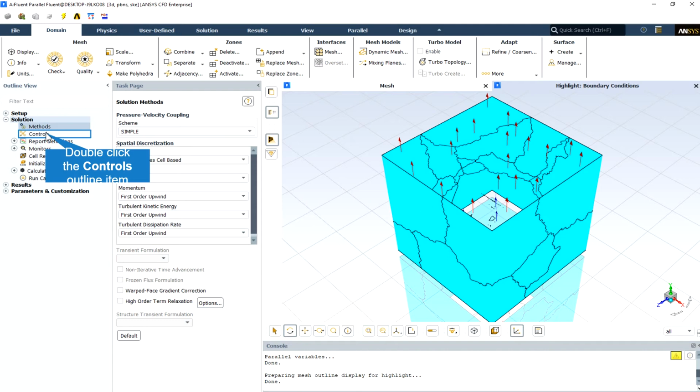For example, if you are running a high Mach number flow calculation that has an initial solution much different than the expected final solution, you will usually need to perform a few iterations with the first order scheme and then turn on the second order scheme and continue the calculation to converge, to obtain the convergence exactly.